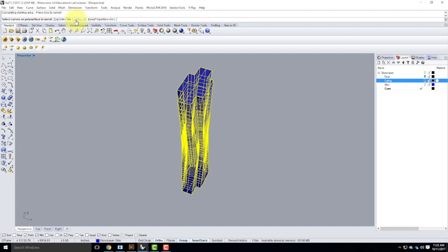The other thing is labels. Do you want them to be on or off? It's really hard to figure out what shapes match up with what without the labels. So I would definitely turn the labels on. So you want labels to say yes. And keep properties as no is just fine. Before I actually finish this, though, I am going to create a new layer so that I can put my shape onto that layer. It just keeps the organization a little bit better. So there it is. I'll go ahead and hit enter.